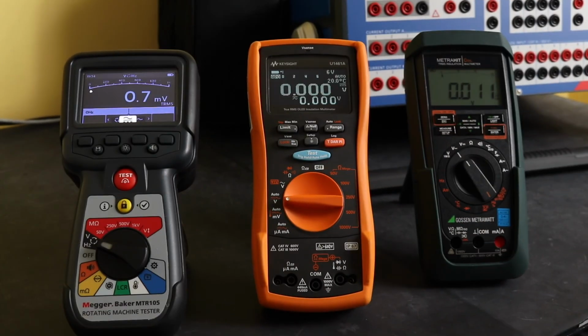So we're at a point in another video where I dish out some points. For me, I really like the three-phase functionality of the MTR105. The voltage measurement and the phase rotation function coupled together is very, very useful for working on motors, and obviously neither of the other two instruments have that kind of functionality. I do accept that the update is a little bit slow on the Megger, and they really need to address that, to be honest. The other point to note with the Megger unit is that it's Cat 3 rated, whereas the other two units are Cat 4 rated.